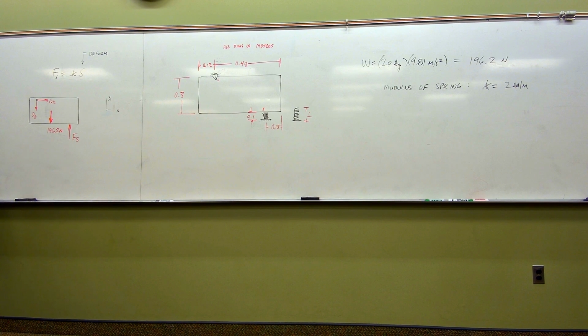All right, cool. So now, this is an important idea. Folks, I want you to look at this. Right now, I got one free body diagram and I got a grand total of 1, 2, 3 unknowns. We all know that with a free body diagram, as long as the forces aren't concurrent, meaning they don't all intersect at some singular point, which these do not, we have a budget of 3 equations of equilibrium. We can sum forces in x, sum forces in y, and we generally will sum moments about some other point. Meaning, with 3 unknowns here, I can solve for each and every one of those unknown forces.